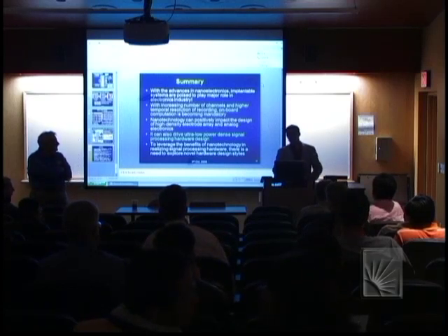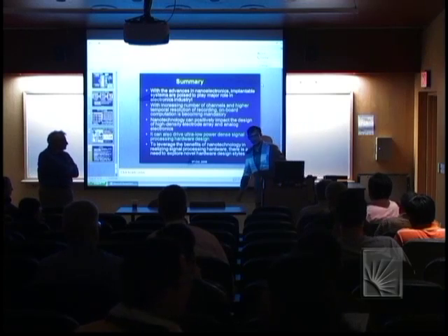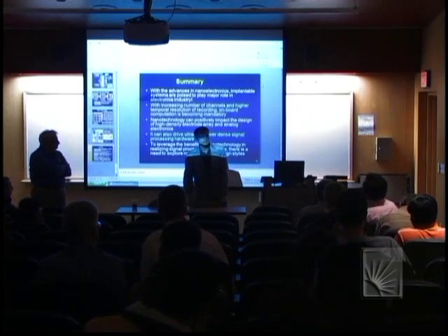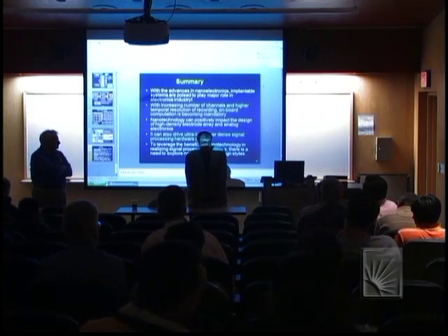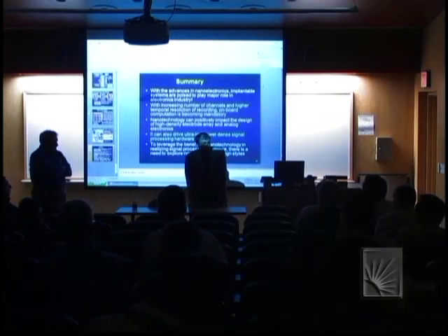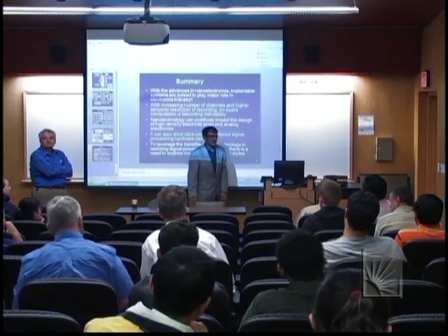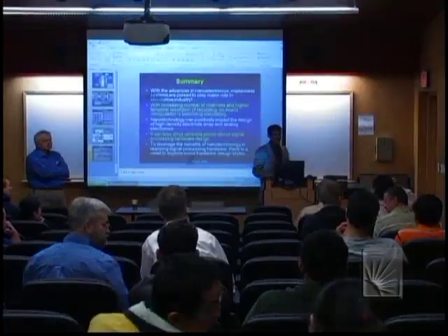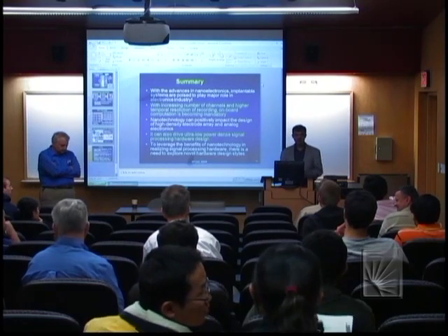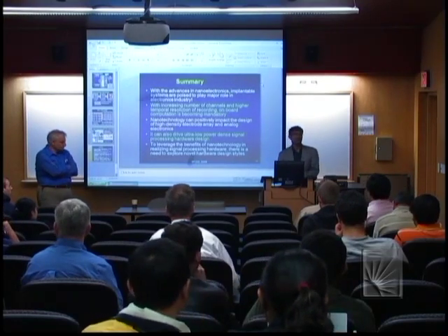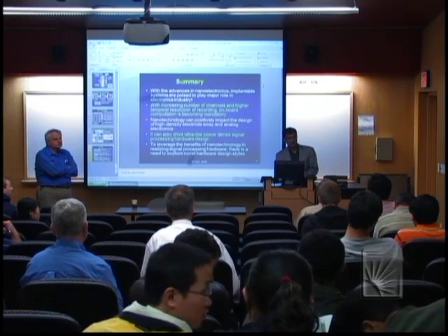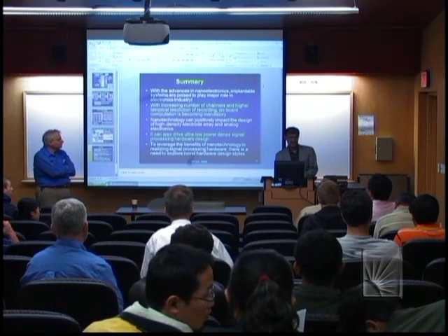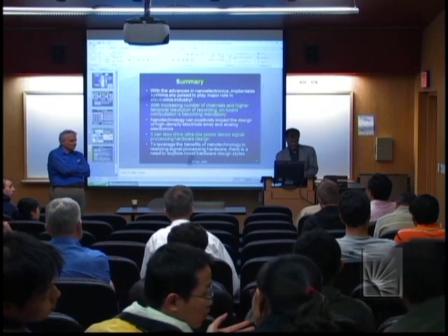Let me first answer the question for analog electronics. Yes, you are right. You may not need to go to 45 nanometer, and if you go there, there will be several issues like robustness, so you have to be careful there. And as I mentioned, analog electronics do not scale as well as digital. I do not know which technology would be good for analog electronics for implantable devices. Steve can answer that question better.